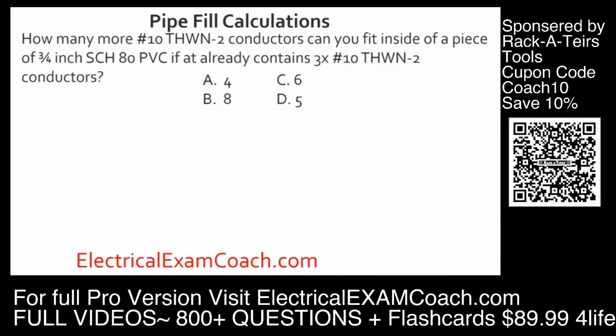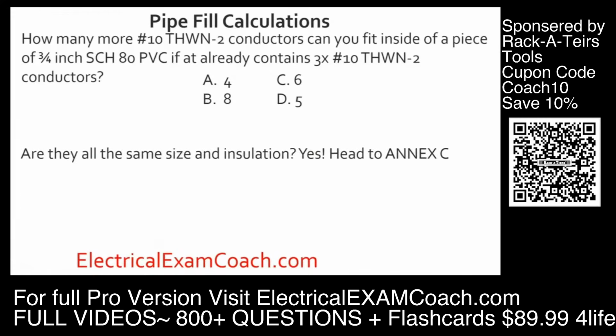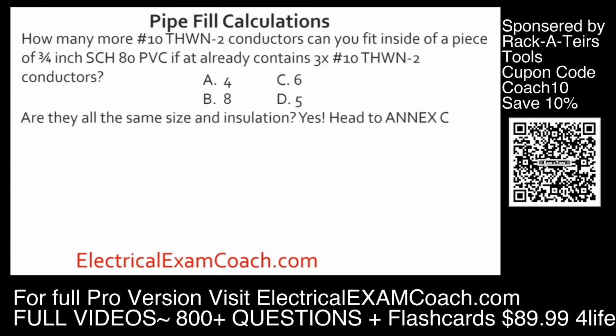How many more number 10 THWN-2 conductors can you fit inside of a piece of 3/4 inch Schedule 80 PVC that already contains 3 number 10 THWN-2 conductors? The first question we're going to ask ourselves, are they all of the same size and insulation type? They are. So we're going to head straight to Annex C.